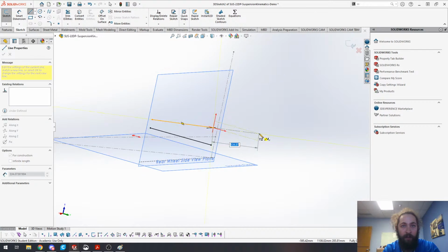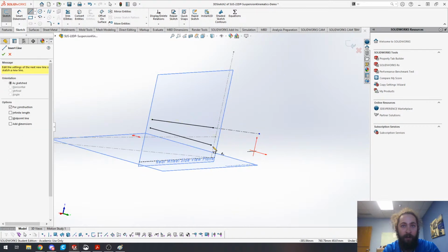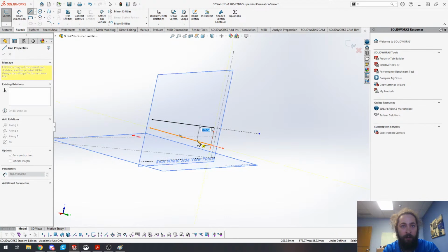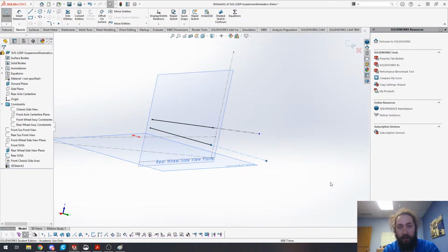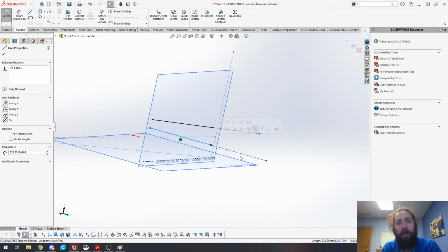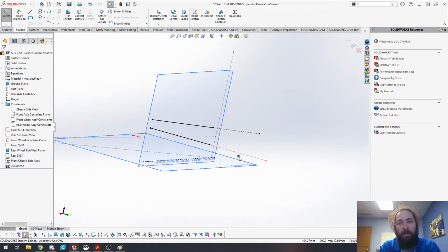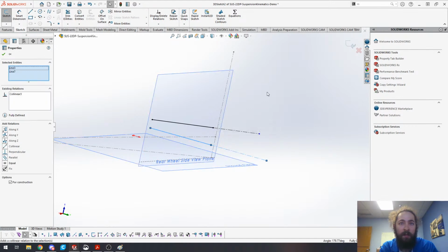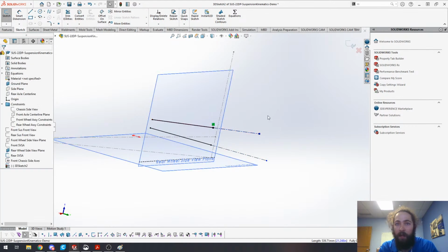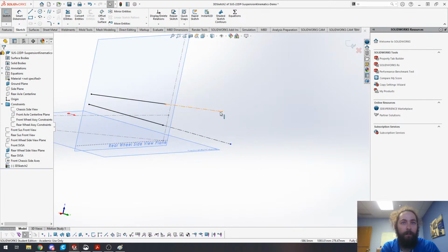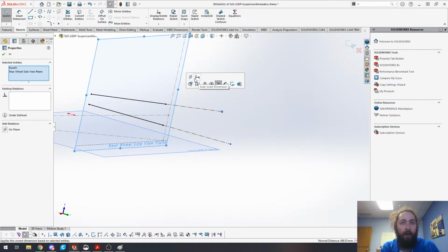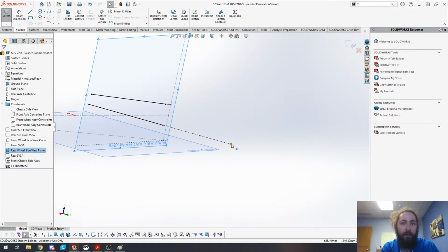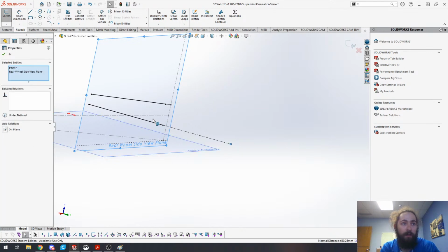Hovering over this brings up the collinear lines, so we can automatically add those constraints in. It's kind of hard to see, but there are some faint yellow dashed lines that pop out after you hover over another line segment, and then you can follow those. In that case, it ended up defaulting back to the y-axis, and that's collinear. Okay, cool. Add our on-plane constraints. Same thing there.